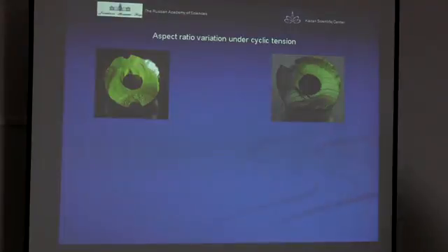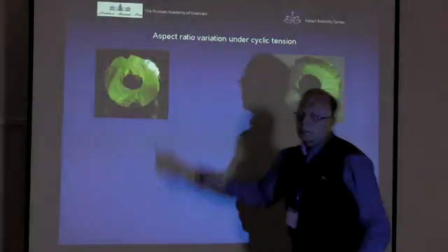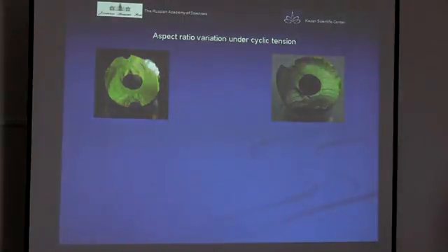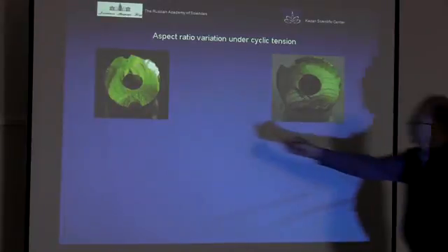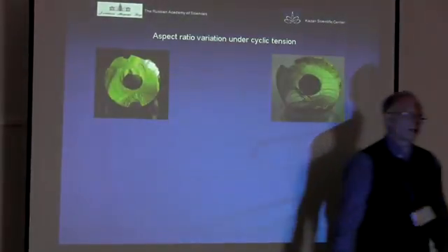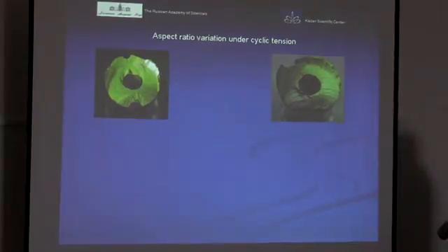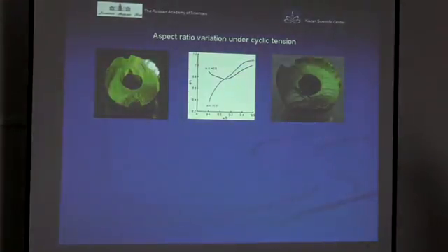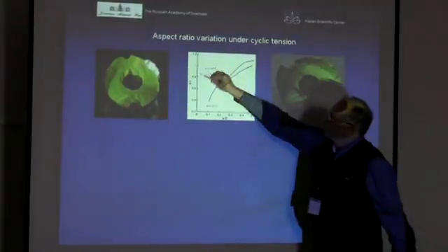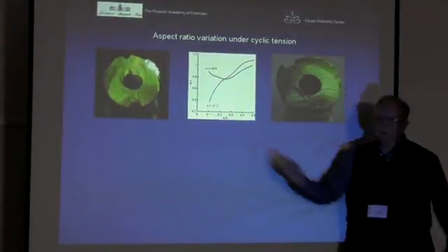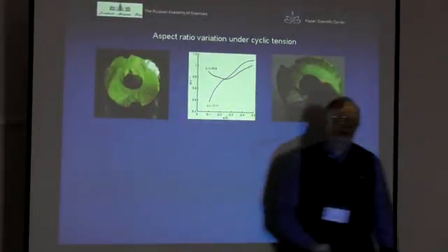So, during our test, we fixed the crack front position by changing the R ratio. We fixed the maximum amplitude, but changed the minimum value of the amplitude stress. As a result, we got the position of the crack front for the initial cylindrical crack front and another one. And as a result, we got the relation of aspect ratio as a function of dimensionless thickness.